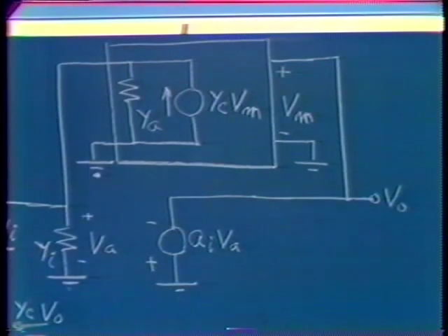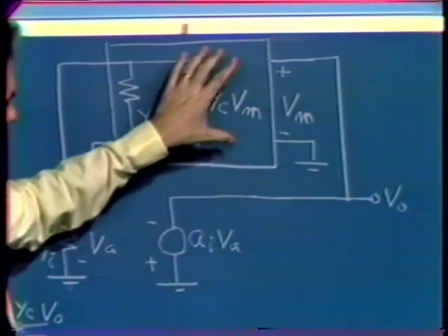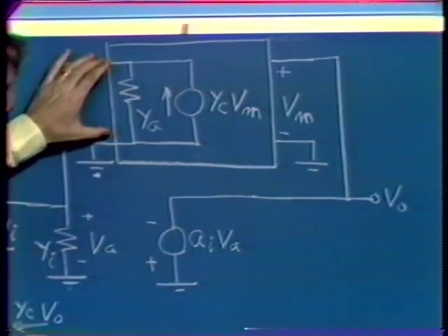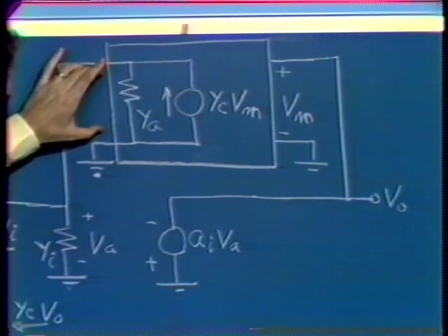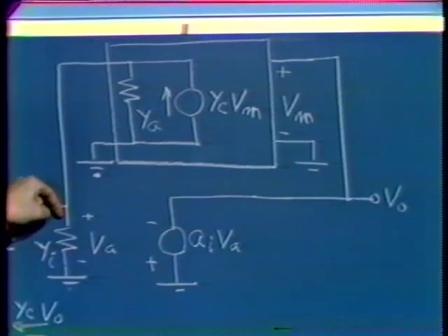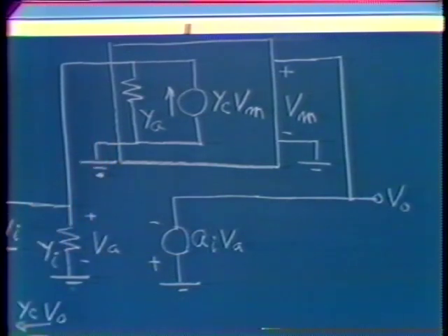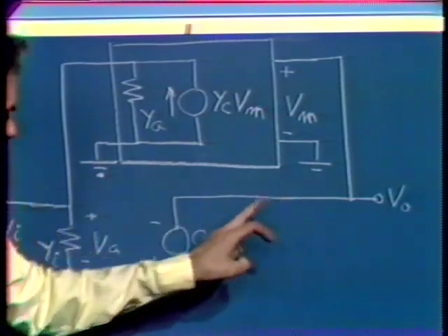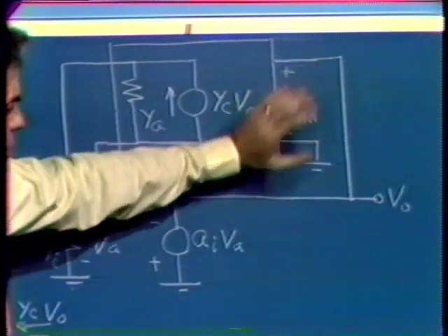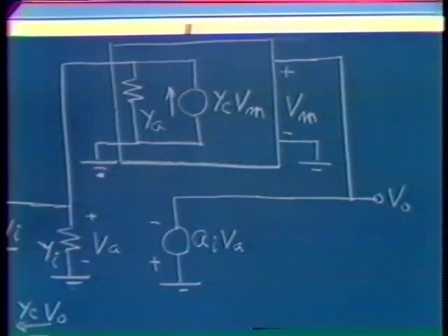We then form a minor loop by connecting a compensating network from the output to a two-port network, and the second port of the two-port network is connected back to the input of the second stage. We'll find it convenient to represent the two-port in terms of its short-circuit transfer admittance. At least as I've shown things, where we apply the voltage from a voltage source to one side of the two-port, we don't have to worry about parameters of the two-port at this side of the network.